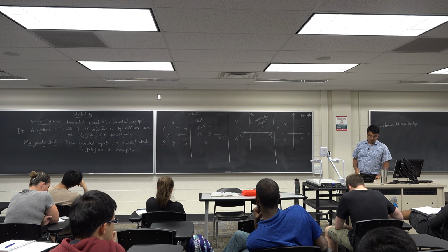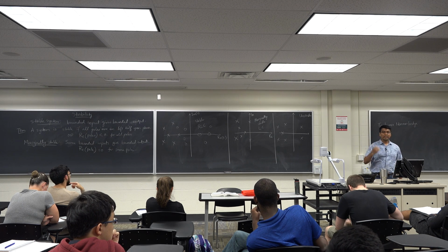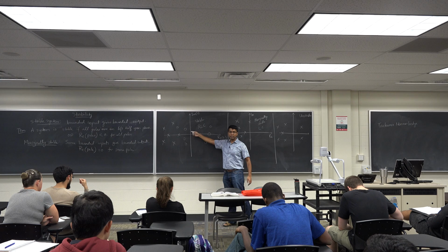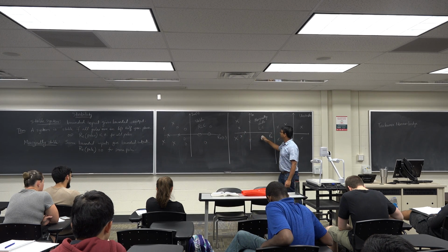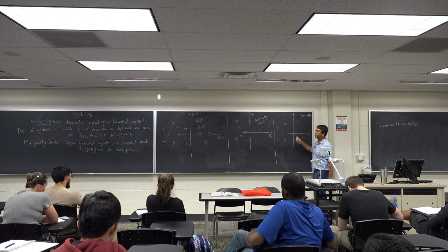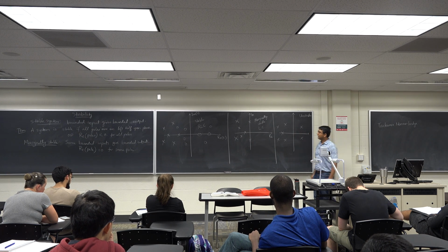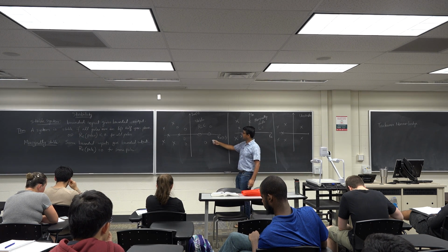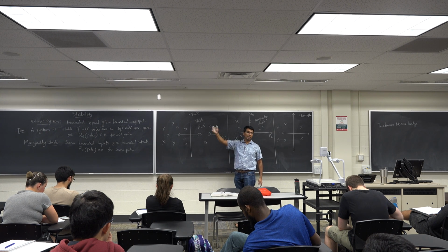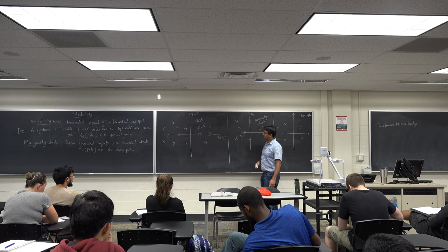All right, so I hope the concept of stability is clear. There has to be a dissipative element in the system in order to make things stable. If you do not have a dissipative element, your system could be marginally stable or it could be unstable. And the dissipative element has to convert energy in one form to some other form, which can then be dispelled to the external environment.